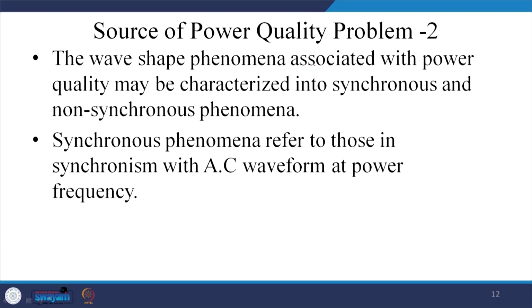Now, the sources of power quality problems, which may be many. The waveform phenomena associated with power quality may be characterized into two broad categories. One is synchronous, that is a 50 hertz problem and its harmonics, and the other is non-synchronous phenomena like lightning strikes and all those issues.